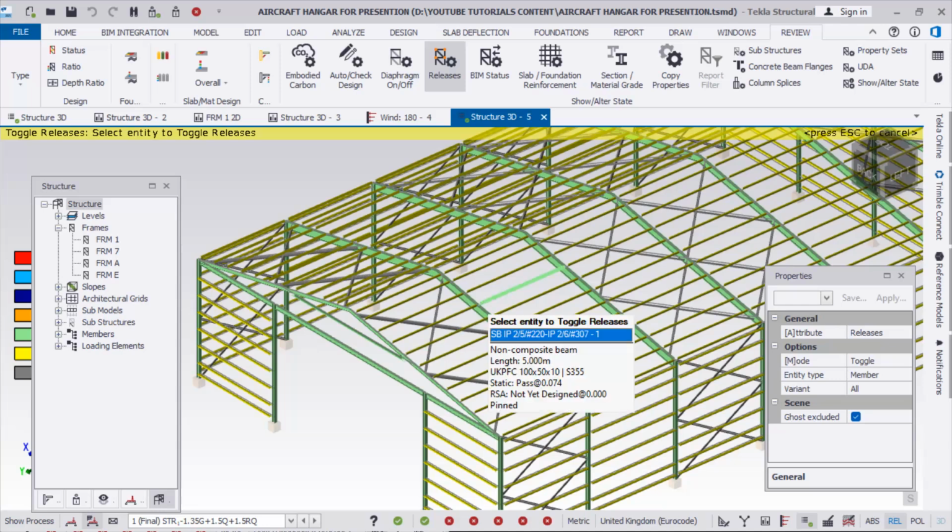So that's to tell you that your beam is less likely to fail through deflection because you have already resolved that by distributing the moments to the supports. And that is a very perfect way to economize your design because you're going to use smaller sections and less deeper sections. And when you do this, what is going to happen is that the cost of the design is going to be low.